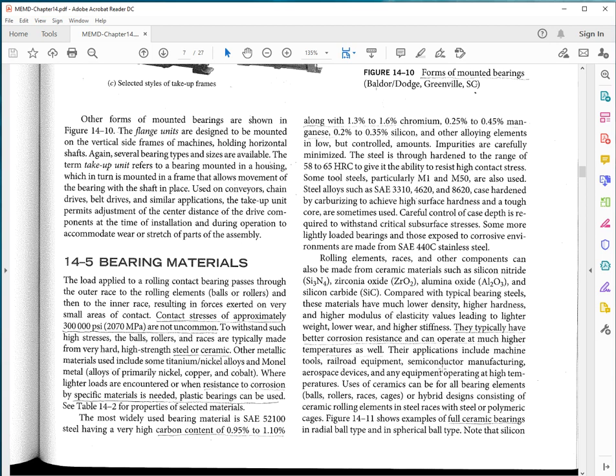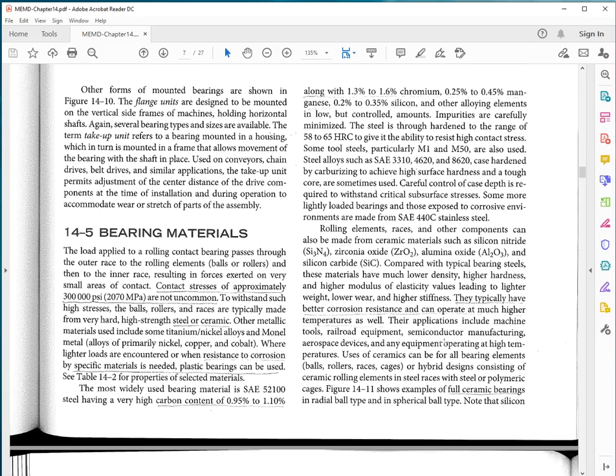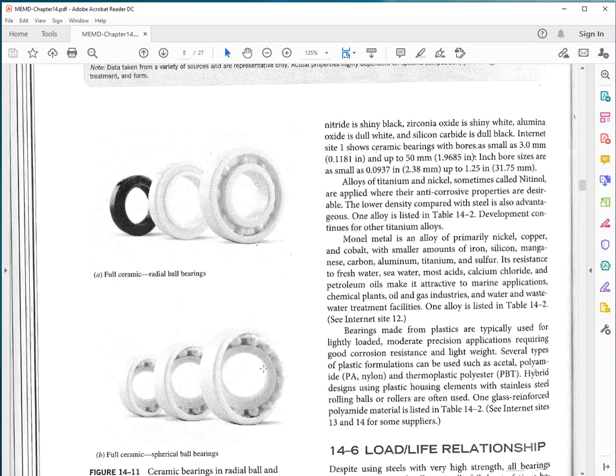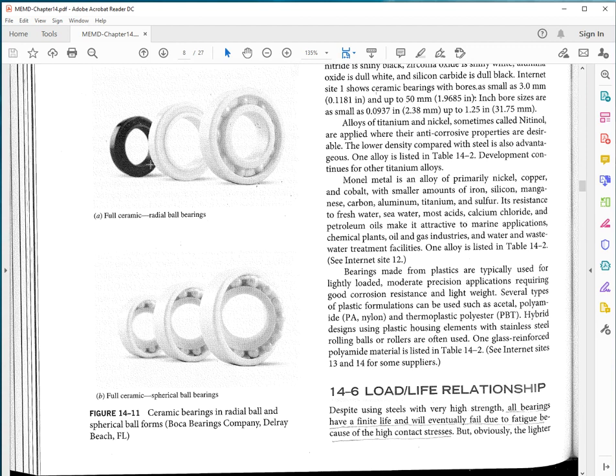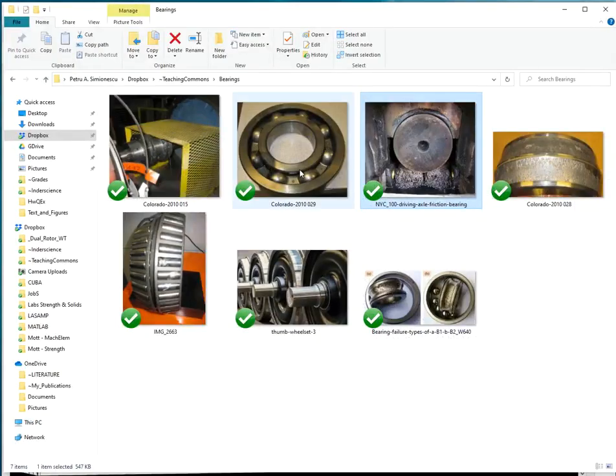Rolling elements, as well, the entire bearing could be made of materials other than steel, of ceramics, for example. So these all would be non-conductive bearings. They are desired, even if only the rolling elements, when used with electric machines,